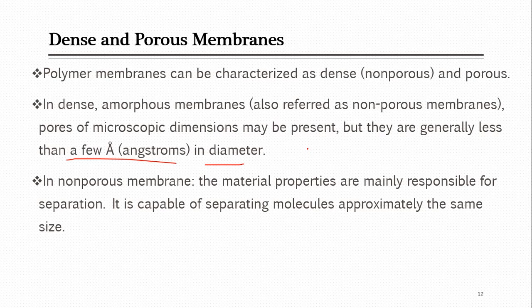Here, the material which can diffuse through the membrane can easily be separated from the other material which can't diffuse, and with the help of these membranes, even a feed in which there is more than one component of somewhat similar size can be separated. How? Because here you can separate them not based on size but based on other properties of diffusion through the membrane material.